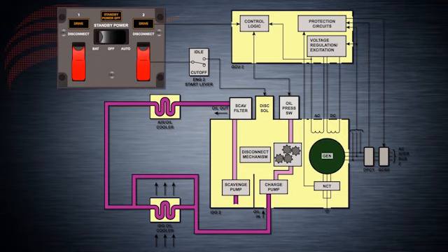Each IDG has a constant speed drive section and a generator. Part of the generator drive section is an IDG air-oil cooler that decreases the temperature of IDG oil. Similar to engines, oil is used in the IDG to lubricate and cool down moving parts by minimizing metal-to-metal contact, thus reducing friction.